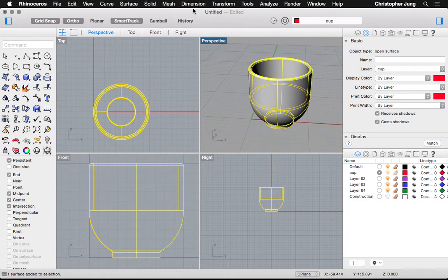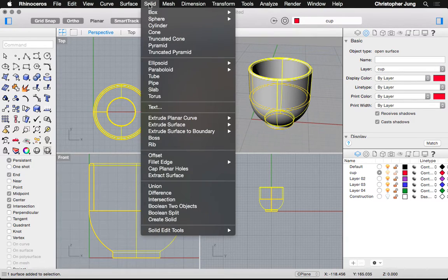And we do this through Boolean commands. It's right here. Oh, it doesn't say Boolean, but basically, here it is. Boolean, two objects. We're going to use union. That's probably the easiest way to connect two objects. Oh, actually, union only works when things are intersecting. So I've got to use Boolean difference, because they don't actually quite touch. Boolean difference is basically you can take two objects and it'll work its damnedest to connect those two together. So you do want the thing to look like what it looks like, but you could get interesting results otherwise. So I'm going to hit difference,